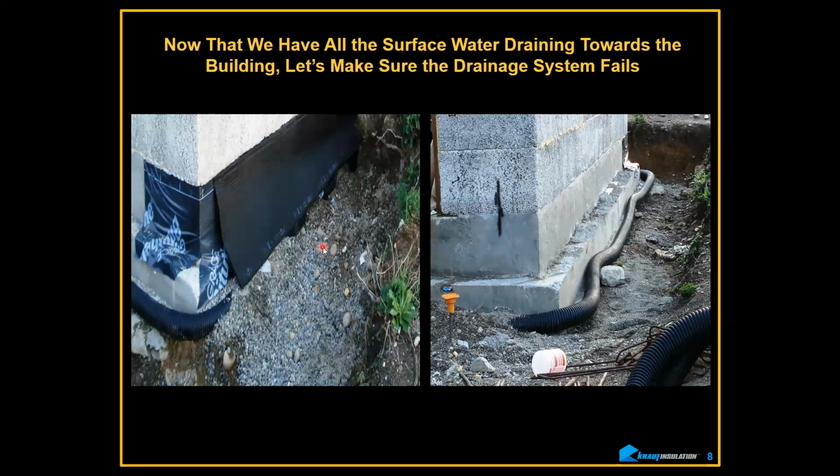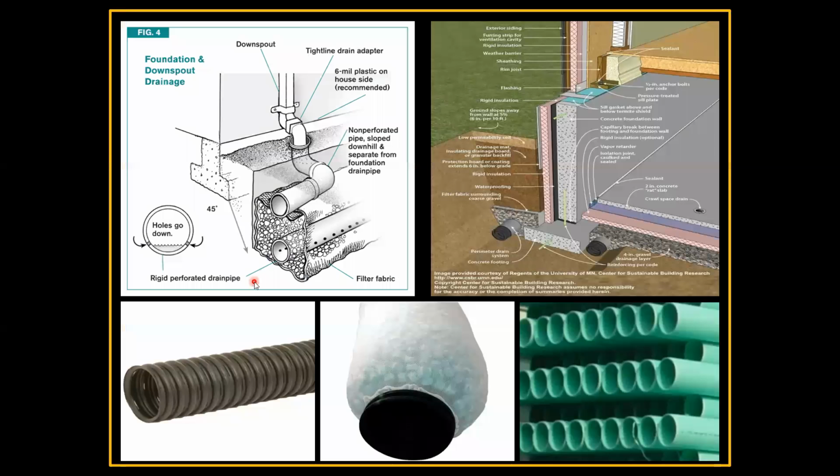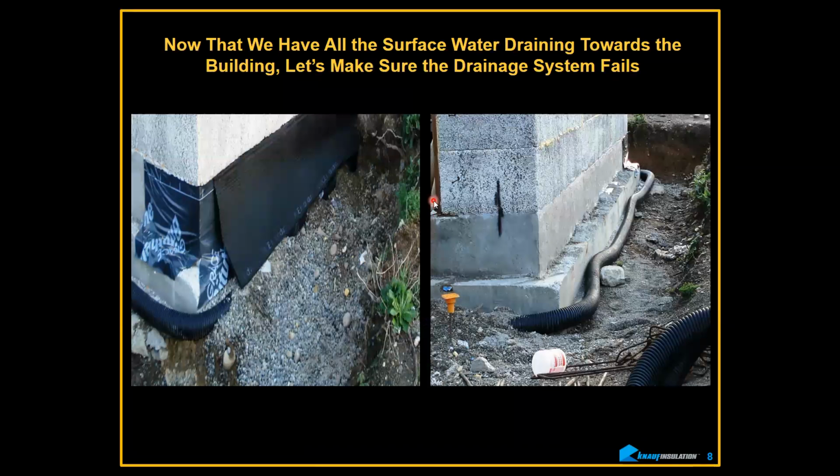This drain mat is supposed to have a terminal strip on top of it, and it doesn't. That's another problem. It's not about the backfill falling down. It's about it separating from the wall over time and getting debris behind it. It's also really not connected to this pipe. It just isn't connected, and it really needs to be. This drain mat needs to go all the way down to the filter fabric. Of course, there's no filter fabric, as you can see around the pipe. There's nothing. There's tons of debris in here, and that's bad. So if you're looking at drainage systems, pay attention to what they're supposed to do and how they put them together.